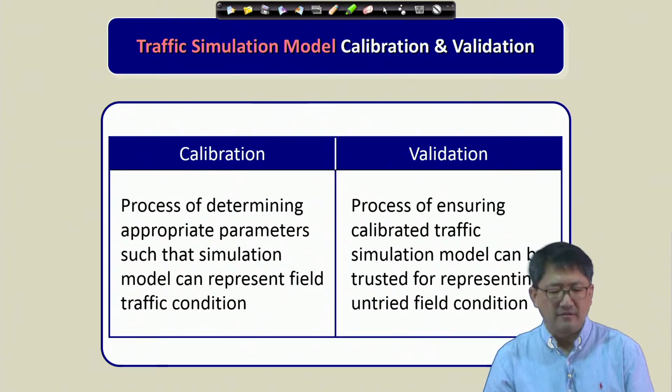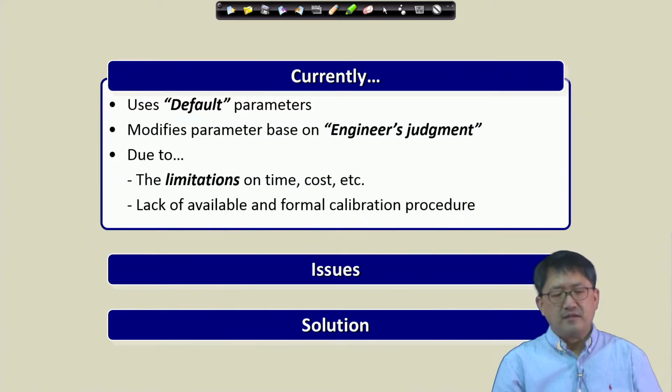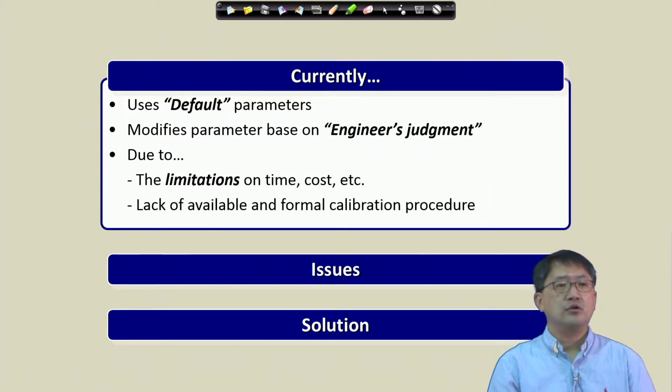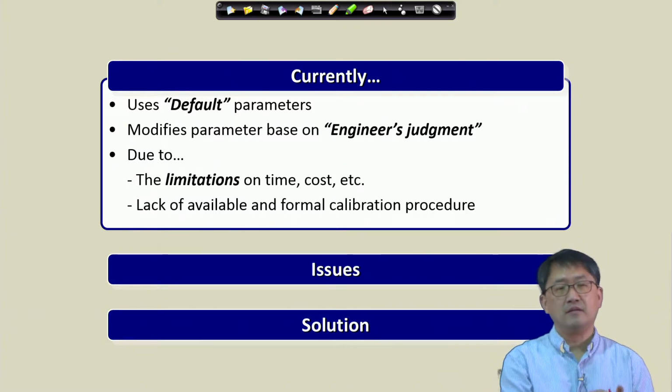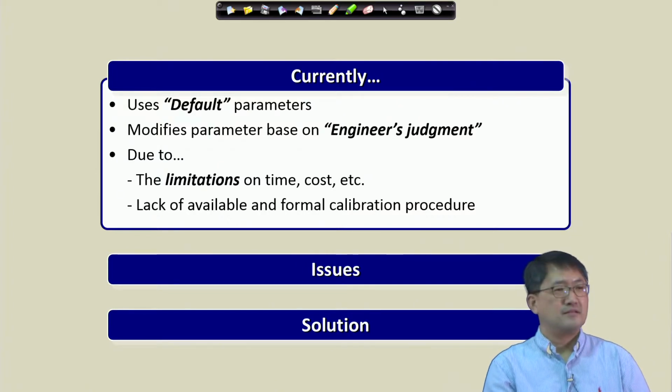In traffic simulation models, same thing. The way I see the calibration aspects is that if you ever use VISSIM, CORSIM, Paramics or AIMSUN, a lot of people actually take the default as a good calibration. People use the default that the vendor thinks is a reasonable value. And when they have to make a change, they collect the data from the field and enter everything they can, run the model, and they don't see the expected results. And now they're kind of worried: what's wrong with this model?